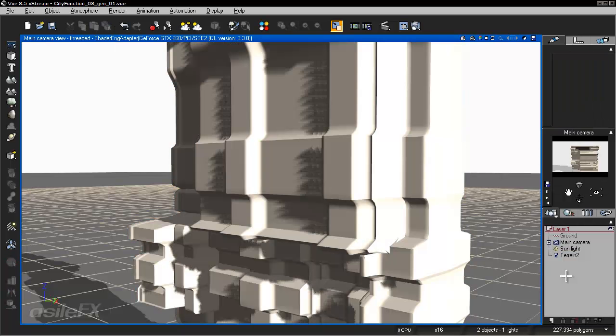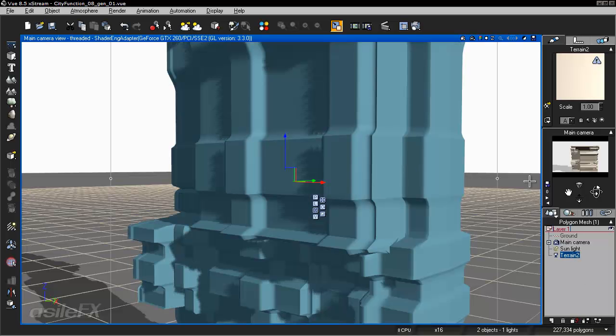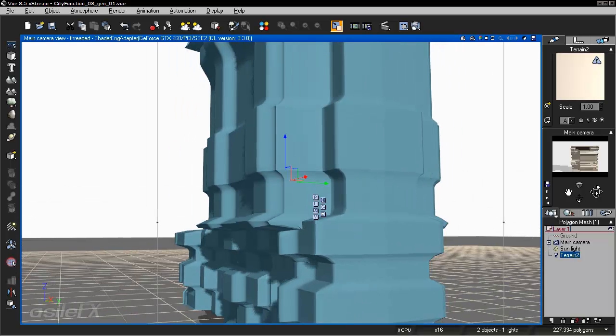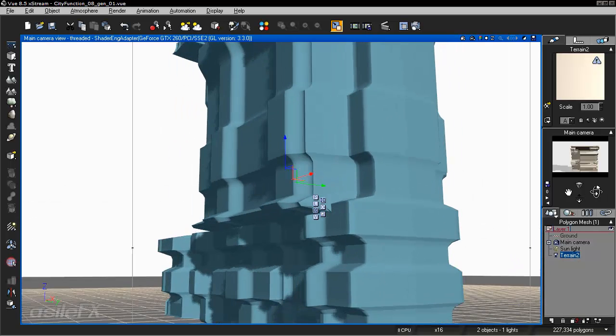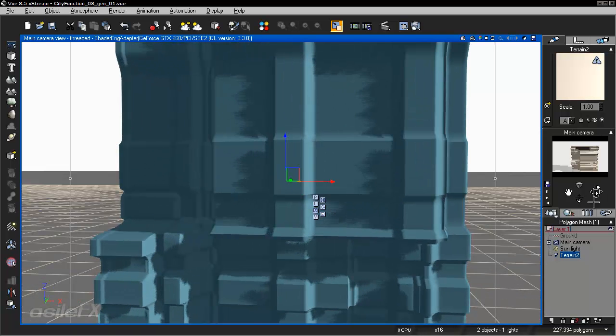If you are exporting, you may also need to manipulate the UV map, because the UV map is going to be a projection of the terrain when it was flat. So you're not going to have a good amount of space in the UV for the vertical areas. So you may want to also reconstruct the UV.